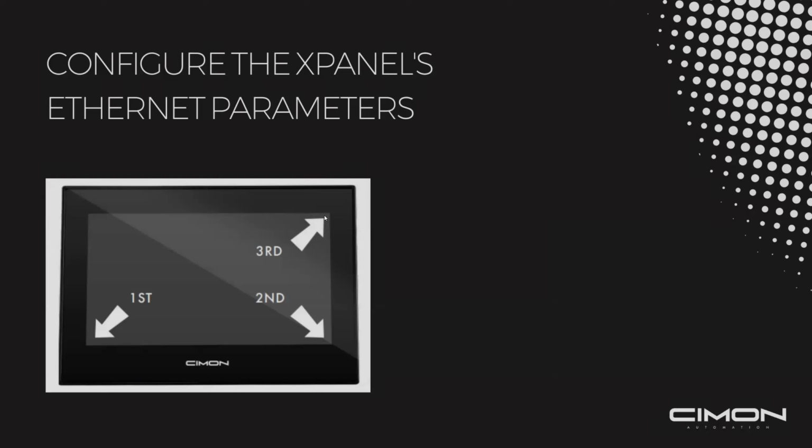So technically, you're going to have three different connections that you can download to the X panel or upload from the X panel. And when you have two Ethernet ports, the beauty in that is you can allocate one to be like for a WAN network. So maybe something talking to the cloud because we offer cloud-based protocols such as MQTT or OPC UA. So you could talk to AWS or Azure, what have you. And then the other Ethernet port can be allocated to your LAN network.